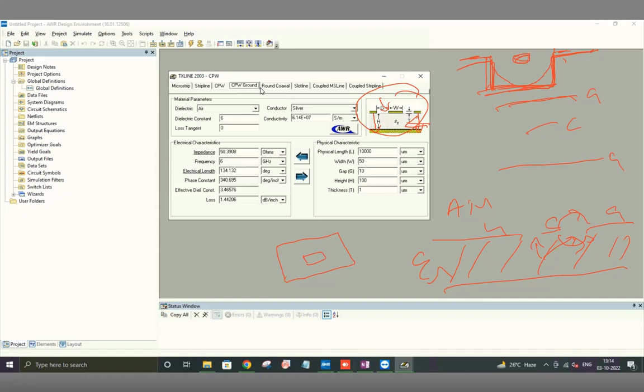And these holes are for making sure that both the things are aligned, the holes which go straight down, going all along the line. And by the way, if you're seeing them for the first time, to orient you, there are 6 transmission lines here. They're all coming from the edges and going towards the middle. Some of them share the same ground plane, but that's okay. For every alternate one, the middle ground plane is the same, but you're not going to have fields going much beyond the edges. So there's no fields here you have to worry about.